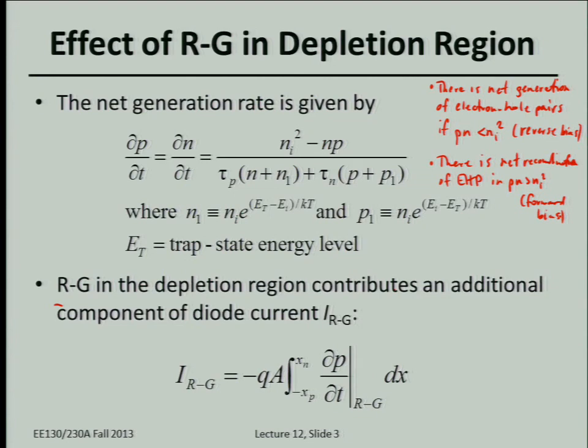So you basically have, for each electron-hole pair generated, the electron going to the right, which is negative current. So that contributes negative current at every location. Well, I mean, it generates negative current. Eventually, it flows past all of the locations to the right. For the hole, it flows past all the locations to the left. So basically, it's like one charge on net, like one electron flowing from the left to the right. Does that make sense?